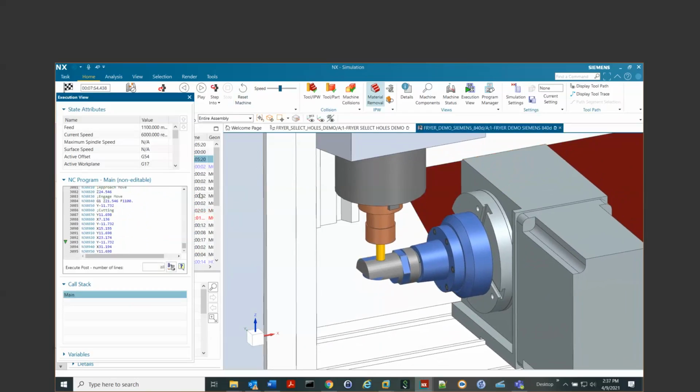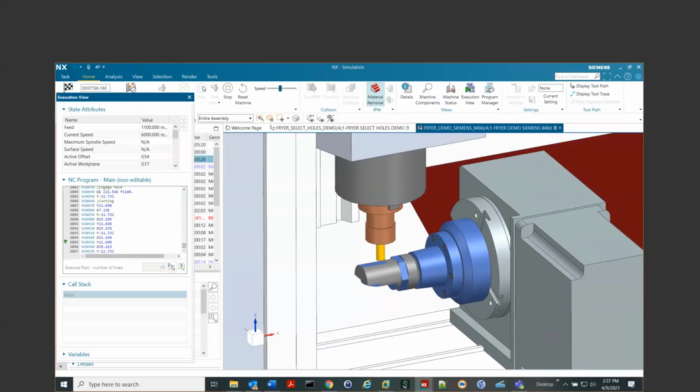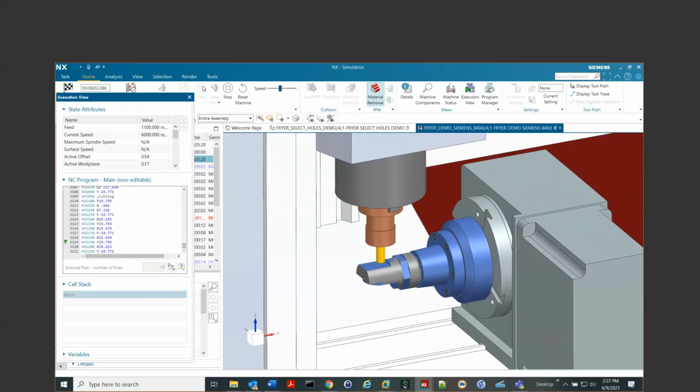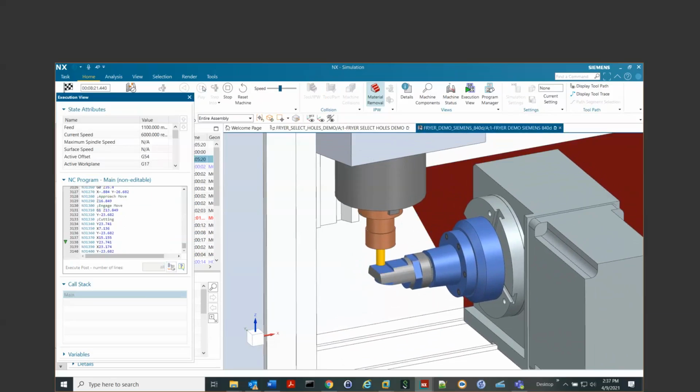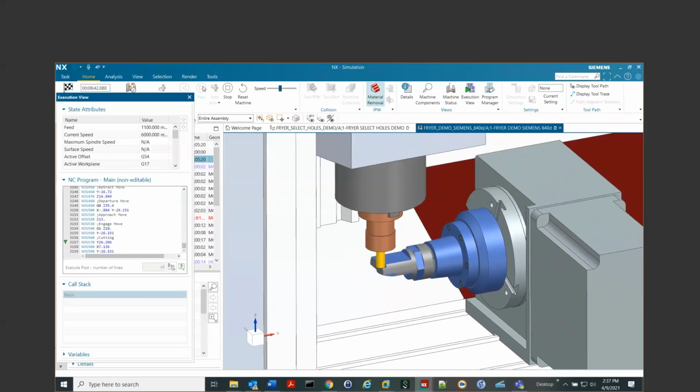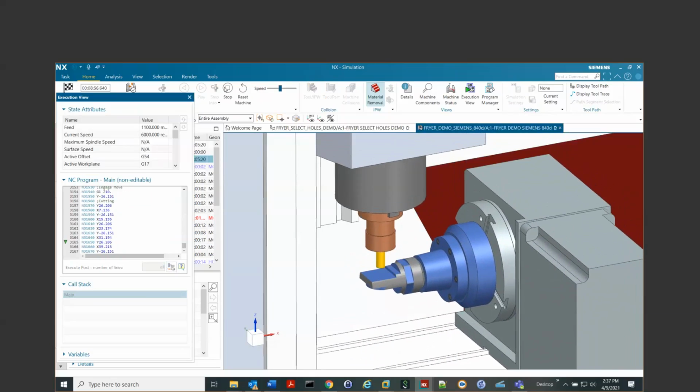Let's stop this here too. Here we're doing a floor wall operation, but here I chose to take it in steps to show, even though we're just machining the top of the part, the end mill is not going back and forth to the extents of the part. It's only clearing the part by what it needs to, because we work with a true solid, so it sees that radius there, and we do not have to go all the way to the extents of the part to clean it up. Look at that. That'll save some time, especially on a big part.